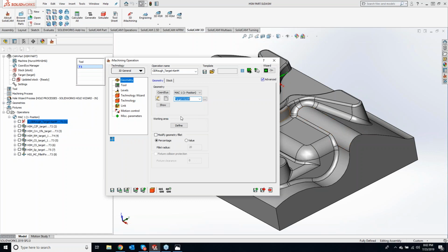Now, when it comes down to tooling for a part like this, if you ask myself, I would definitely 3D iMachine this out. But if you guys talk to other guys, they may want to use HSR, and the different tool paths in there. I'm kind of going back and forth with the differences here, but the reason why I would go with iMachining is, one, I can use my flat end mill, so I can use my roughing end mill to go in there and rough everything out. You can use a ball end mill with 3D iMachining, but you're not going to get as good of a cycle time and tool life as you would with a standard flat end mill.